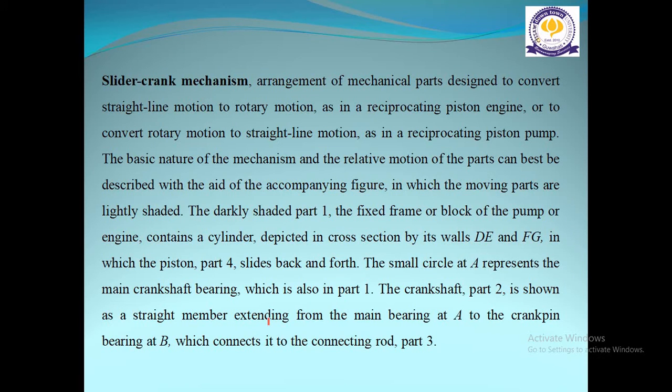Slider crank mechanism: an arrangement of mechanical parts designed to convert straight line motion to rotary motion, as in a reciprocating piston engine, or to convert rotary motion to straight line motion, as in a reciprocating piston pump. So the basic nature of the mechanism and the relative motion of the parts can best be described with the aid of the accompanying figure, in which the moving parts are lightly shaded.